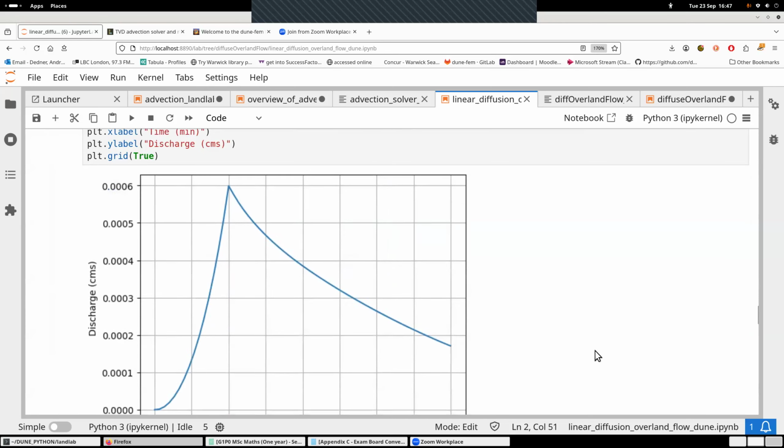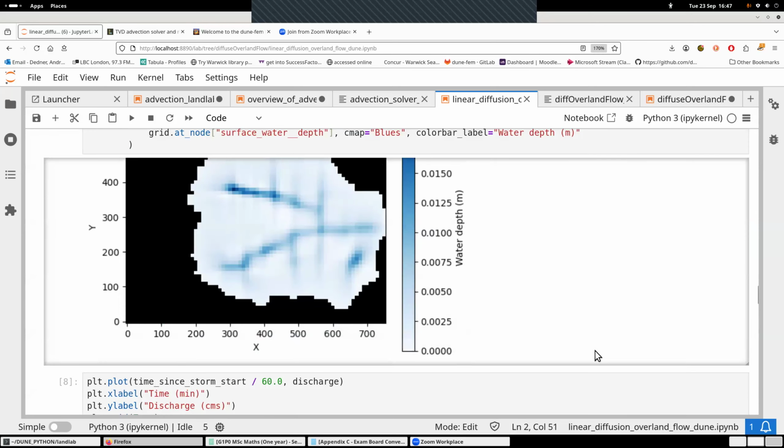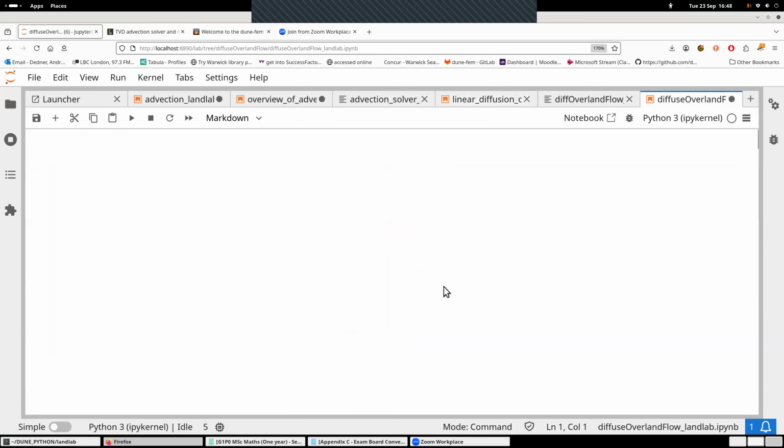And this is the discharge. Here one sees, of course, differences between how the LandLab grid and the Dune grid would work. These are actually still cells for us, so we define the boundary conditions really on the edges of the domain. My understanding is that in the LandLab case, boundary conditions would be given basically here, so at this point the water height would be forced down to 0, or would just stay 0. So there are of course differences in the connection between the LandLab versions and the Dune versions, which do then also lead correspondingly to differences.